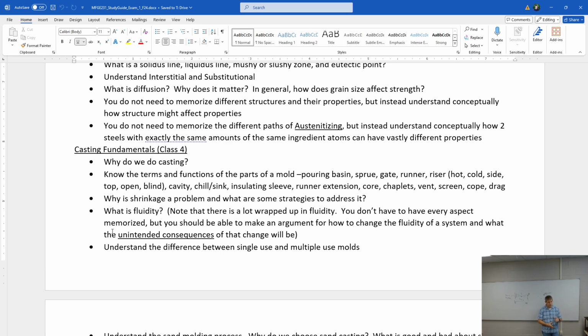And the shape of the little groupings of interstitial atoms will be such that they cause fracture to happen. So to get around that, after we have cooled it quickly, we can heat it back up into the recovery region for a while, and we can allow those to disperse some, and that will allow us to gain some ductility back. So is it just the rate at which you cool? The rate at which you heat it up doesn't necessarily matter? For what we're talking about, we'll say yes. It actually does matter, but for metallurgists to know; we don't need to know. Is reheating it back up also part of the austenitization process?